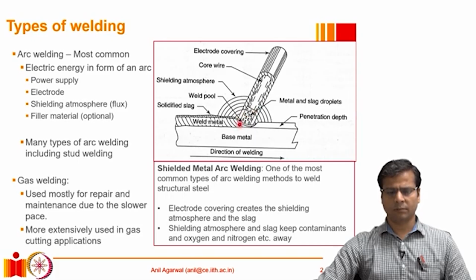the molten metal area. After the flux compounds have burnt, their residue gets mixed with the molten metal. However, since it has a very different density than the molten metal, it tends to get deposited on the surface of the weld. That deposited, consumed flux material is known as slag. And that slag actually has two purposes.